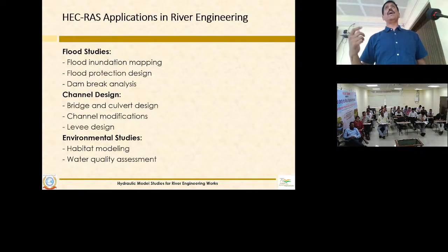Then there is dam break analysis. HEC-RAS has a specific module for dam break analysis where you can specify the dam breach parameters, and Ali sir will be explaining how these dam breach parameters are given in the model. There are empirical equations and physics-based equations. Both can be incorporated in HEC-RAS depending on the scenario, the type of dam, and what flood you are expecting. That model can be run.